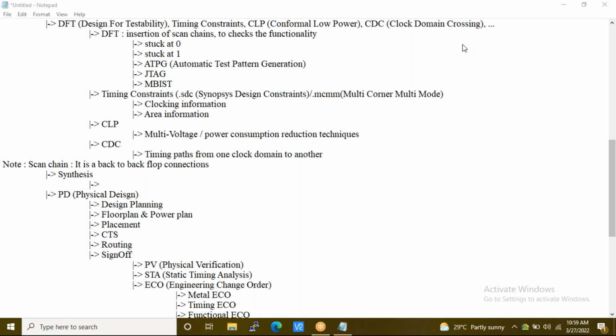Right? Basically, you are walking. Then for 5 seconds, you walk along with the bus. Then you jump into the bus. The same concept is what we apply in CDC also. What we do? We use synchronizers between clock domain 1 and clock domain 2.